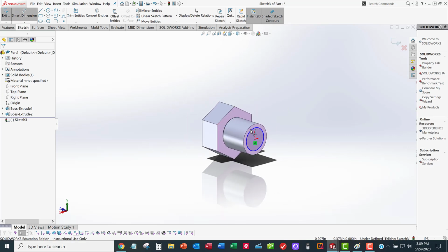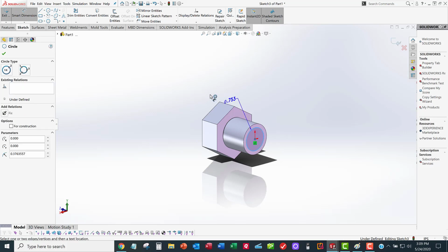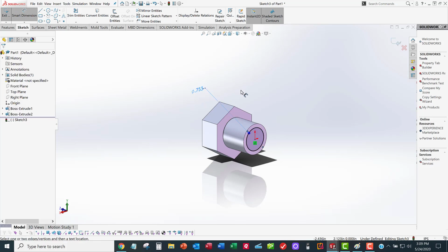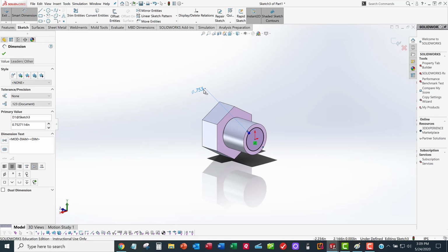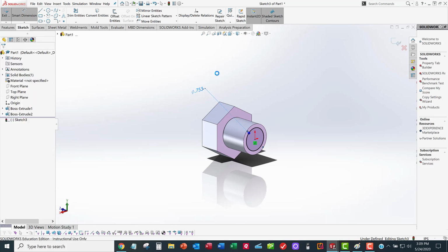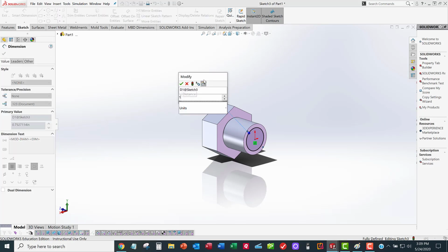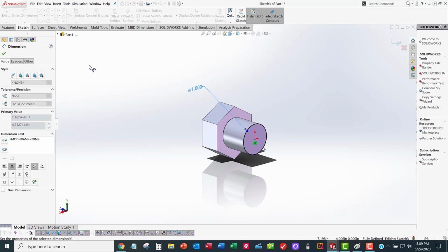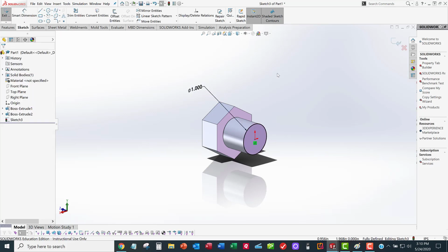I'm going to do a dimension, and I want there to be an edge there, and so I'm not going to put in 1 again because, well, I'll show you what will happen. If I put in 1 here, and then I extrude, now that sketch is fully constrained.